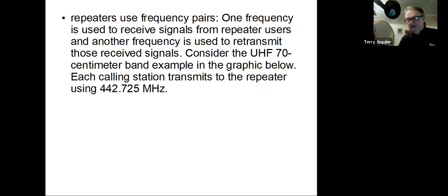And if you've ever given it much thought, if you were to take a cable from your radio and connect it to another radio, put a T connector in it and hook it to an antenna, if you were to key that radio, it would blow out the front end in the other radio. So that's what we're getting into here in a little bit.